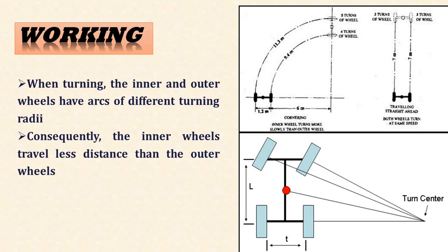So first condition, when the vehicle is traveling straight ahead. The crown wheel turns the cage. The turning cage makes the pinion gears and axle side gears move around. However, the pinion gears do not rotate on the crosspin, and apparently there is no relative movement between the teeth of the pinion gears and side gears.